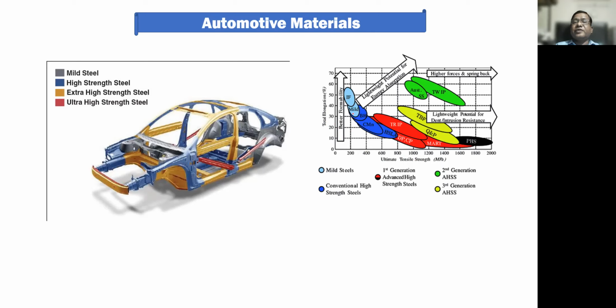First they were using mild steel, then different grades: HSLA, TRIP steel, dual phase, bainitic and martensitic, precipitation hardened and interstitial-free. Depending on the different applications, some parts will have different requirements of strength and ductility. So there is a combination of materials in case of automobiles.